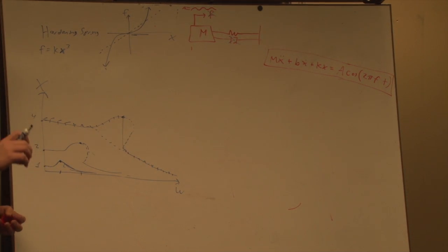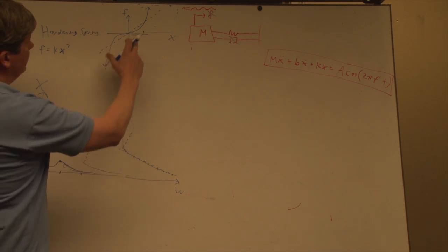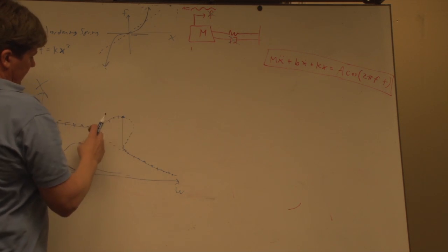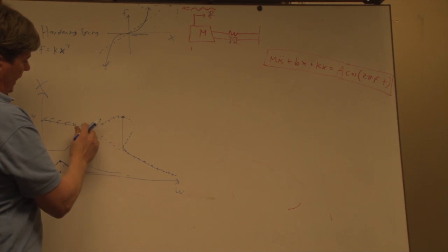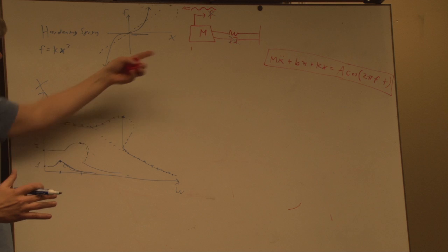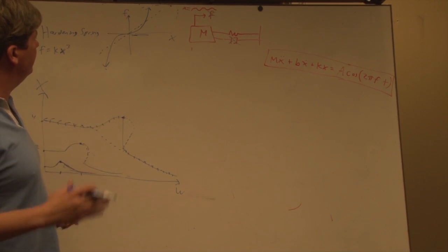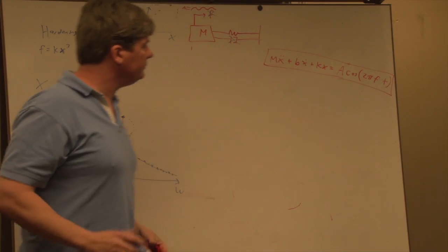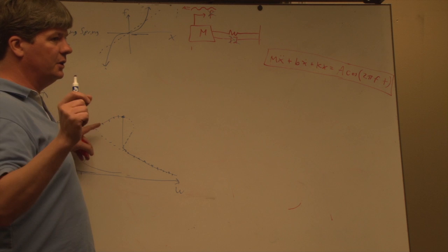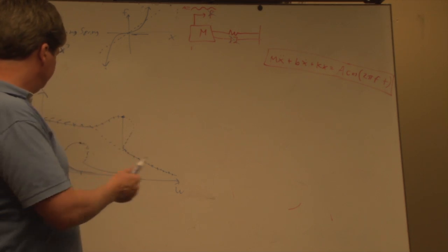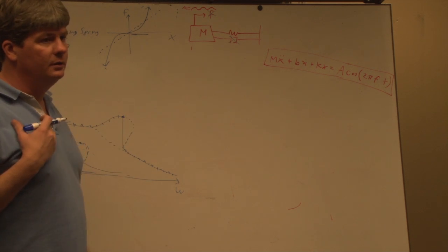Does that make sense? Because in order to get back to resonating, you have to get to the amplitude that matches it. So in these systems with a stiffening spring, if you're driving it with a sinusoidal force, you have to slowly up your frequency in order to get to your resonance. You can't just jump there immediately, because otherwise you won't have the amplitude necessary to have the stiff spring. Does that make sense?